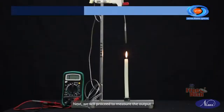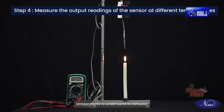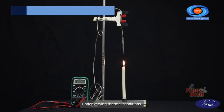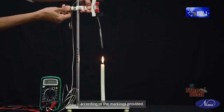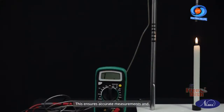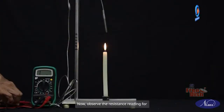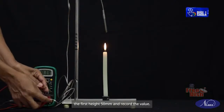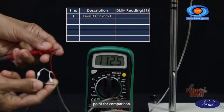Next, we will proceed to measure the output readings of the sensor at different temperatures to understand its behavior under varying thermal conditions. Begin by adjusting the sensor's position according to the markings provided. This ensures accurate measurements and consistent observation of temperature changes. Now observe the resistance reading for the first height, 50 mm, and record the value. This initial reading serves as a reference point for comparison.